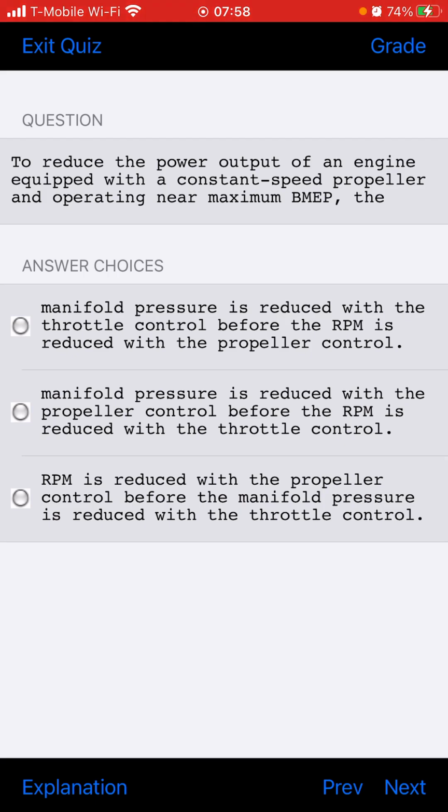Inspect the oil and oil screens or filters for metal particles. Inspect the propeller drive shaft or crankshaft for misalignment. You could do that also.